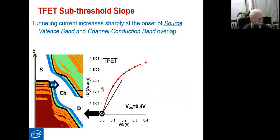So this is our PIN structure. As you can see, this is an N region, this is an intrinsic region, and this is a P region, for example, or vice versa. Sorry, this is P, this is I, and this is N. It's PIN. So this is the energy diagram at, let's say, the thermodynamic equilibrium condition.